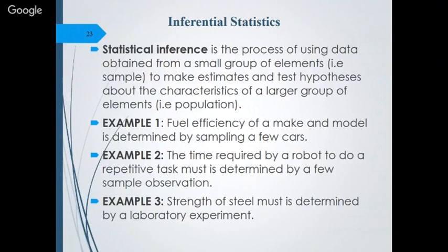So we always take samples to reduce our workload, expenditure, and manpower. We measure the parameters from the selected sample, and we have to generalize them for the entire population. We collect the percentage of defects from the samples and generalize that this much of the samples collected were defective. That indicates that this much percentage of the entire production is defective. So accordingly, management can take necessary action to improve the production technology.